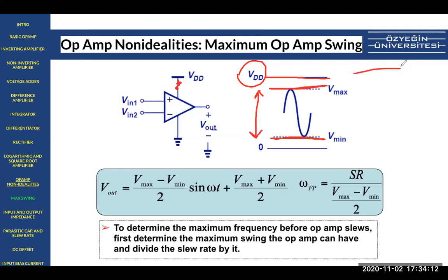When you transmit a signal, there is this thing called a power amplifier, and the power amplifier is the last element before the antenna. So this is your transmitter. And this signal goes to your receiver, to another friend, and you have a low noise amplifier, right? So this part is the transmitter. You transmit through the power amplifier, and what you want to do is transmit a huge power. Why? Because this signal is going to a base station, and the base station might be 50 kilometers away.